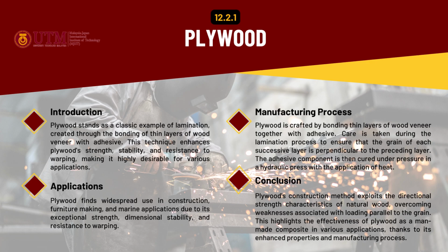with adhesive. This technique enhances plywood strength, stability, and resistance to warping, making it highly desirable for various applications. Plywood's construction method exploits the directional strength characteristics of natural wood, overcoming weaknesses associated with loading parallel to the grain. And these highlight the effectiveness of plywood as a man-made composite in various applications thanks to its enhanced properties and manufacturing process.